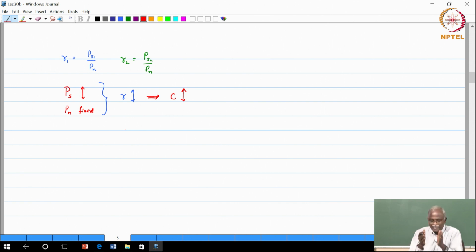Okay. Maybe just one last observation, just so that we link completely with the communications background part. So, how is Pn measured? Why is it constant? Why does it not change? Pn corresponds to N0 times B, correct? N0 by 2 times 2B, but N0 B is what gives you the noise power. So, N0 is your noise spectral density. Okay. What are the units of noise spectral density? Watts per hertz. Bandwidth is in hertz, so the combination will give you watts. Okay. That is the noise power.